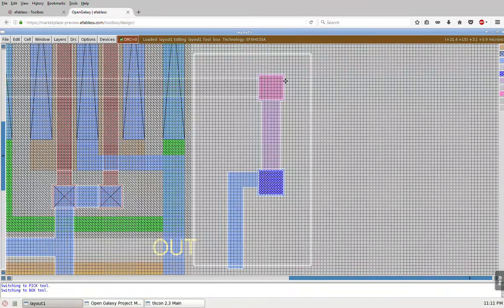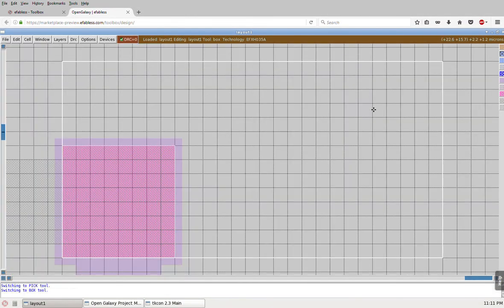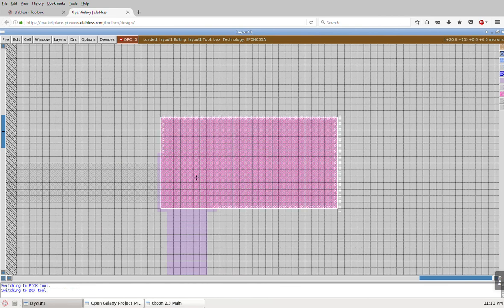Perhaps of interest, and that's always useful if you take a look, the vias over here are not quite a via in the normal sense of what GDS layers are. The material right here in the center is actually a combination of metal 1, this is a via 2, so this would be metal 3, metal 2, and the actual via opening that will normally be inset to some extent inside the via. If you were to make it bigger, you can actually make it bigger. Let's make this via bigger. So I'm going to draw a box that's significantly bigger, and middle click into it. And now my via is much bigger. Now, it will be made of a combination of via, most likely, inside, per design rule, but it's definitely bigger.